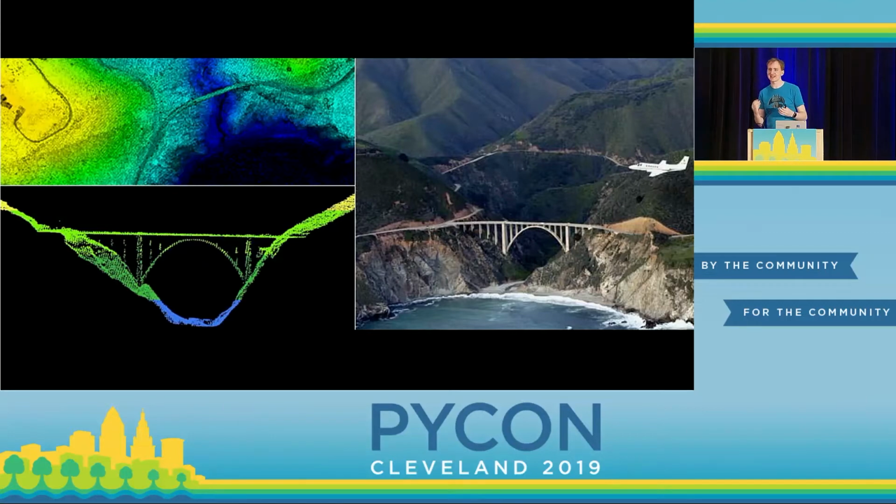But crucially, it's incredibly accurate. It can be accurate down to the centimeter. In fact, these days, more accurate than that. And what this means is you can build an incredibly detailed map, but of a smaller area. LiDAR usually goes on something like an aircraft, as you can see here in the picture, but also can be on a car or other device that moves along and generally maps things around it.